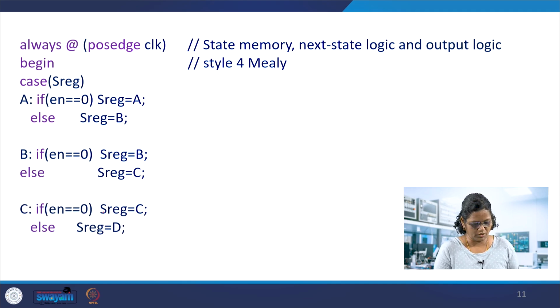See what we have done in the previous cases. Blocking assignments would also work. When you combine this, we will not be able to use the non-blocking statement for the update, because within one always block we cannot combine non-blocking and blocking assignments, so we will get indeterminate results.